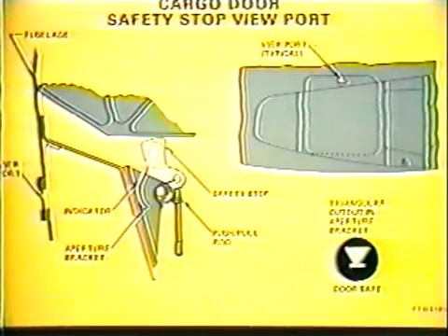The 2 rear cargo doors on the Dash 500 aircraft and all 3 cargo doors on all other L-1011s have viewports installed on the top edge of the cargo door. This viewport, or window, is to be used to visually determine cargo door lock status in the event the cargo door warning light does not extinguish when the door is closed. This concludes Aircraft General.